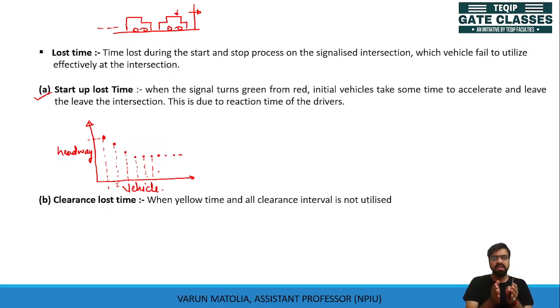So all the vehicles will take the same time to cross the section. This is the time taken by the vehicles which are behind after the start of the move. This equal time which is taken by the vehicles is known as your time headway.